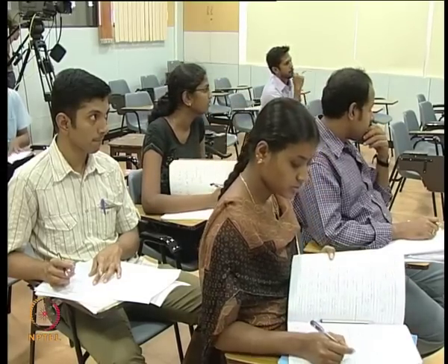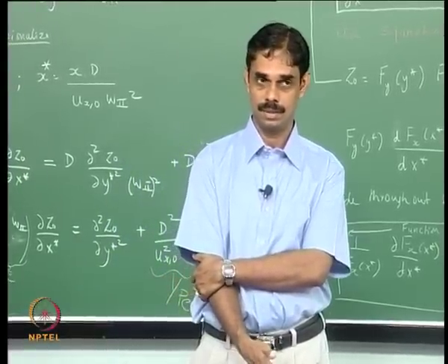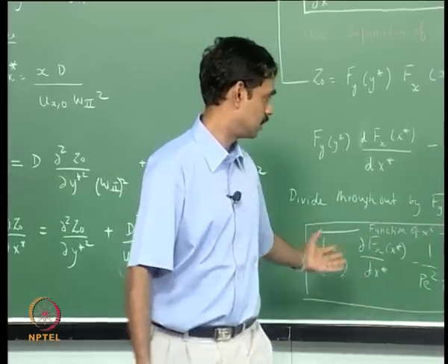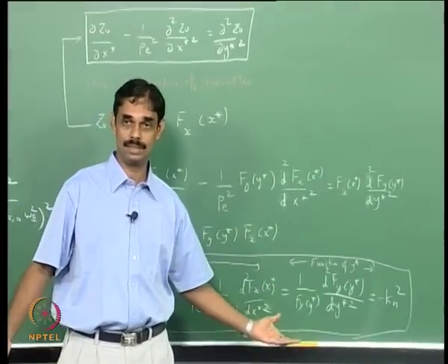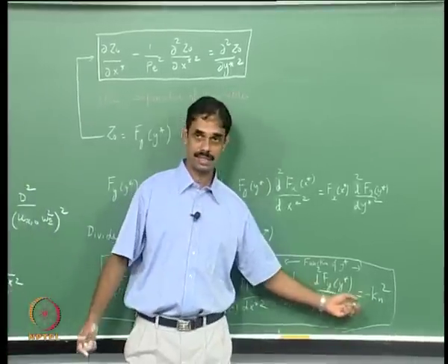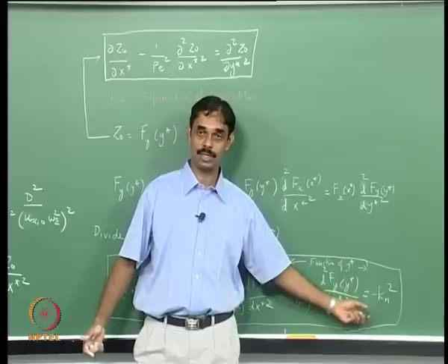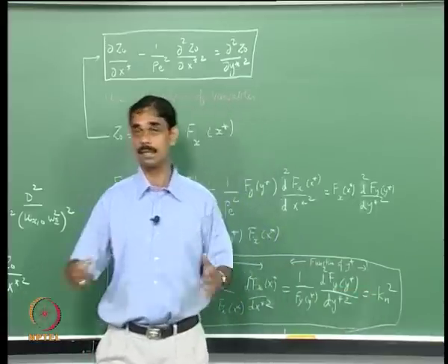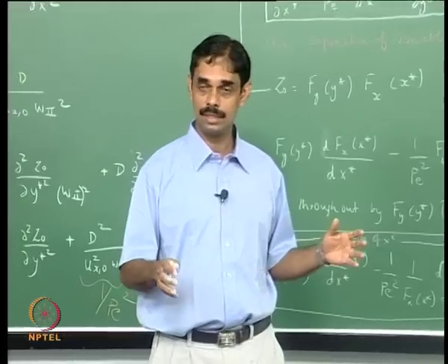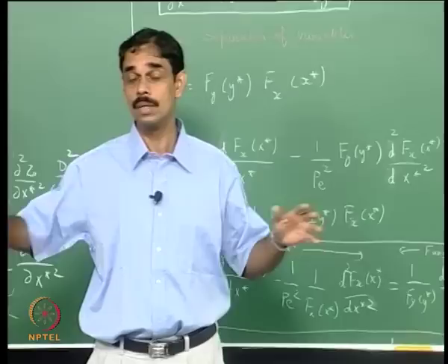Kn is it wave number or it's simply a constant? It's a constant. It is some kind of wave number, but it is not the acoustic wave number, it's some other kind of wave number. Of course here it's just a constant that is appearing, but it's an eigenvalue basically. So we will have to write this. So a lot of kns can satisfy. So based on the boundary condition, we have to find out what kn is there, and then if there are several kns, then this is a linear solution, so we will have to write the function as summation of all these functions over all the kns that are possible.